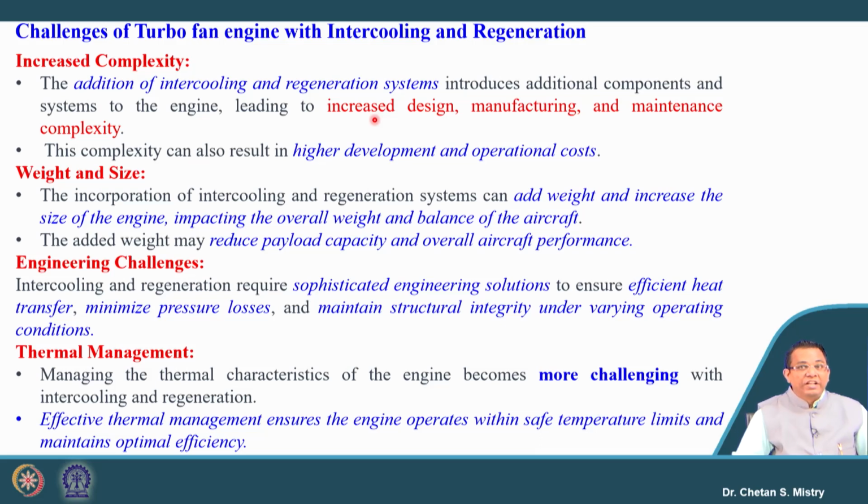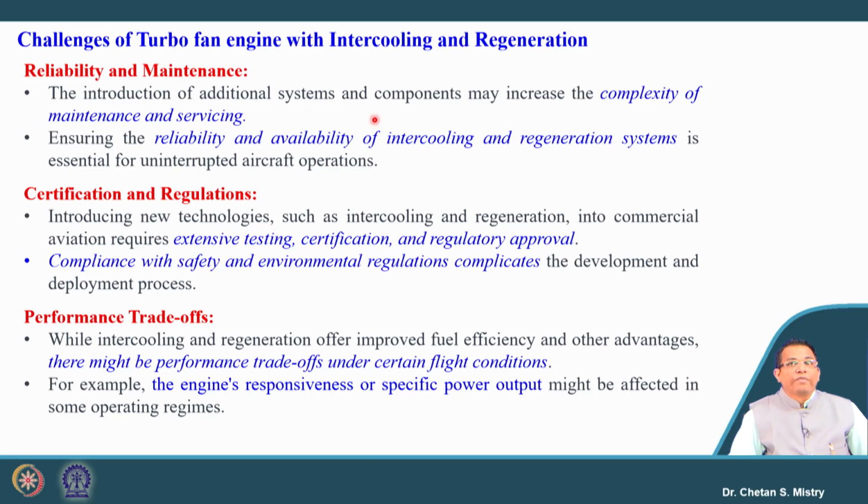Engineering challenges are in terms of effective heat transfer, which needs to be done with minimum pressure loss, and that is required to be performed under different operating conditions. That is very challenging. Thermal management is a big issue for these kinds of configurations. In terms of reliability and maintenance, if we look at the heat exchanger device, let me show you the devices we are using, the intercooler as well as the regenerator.